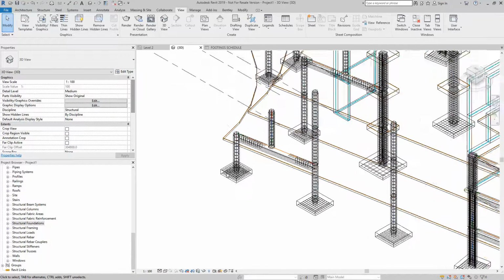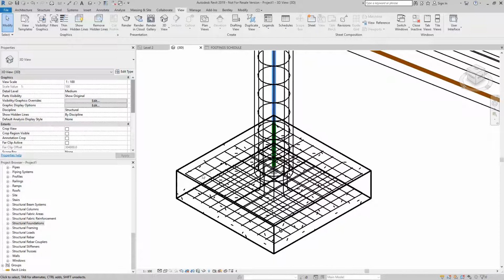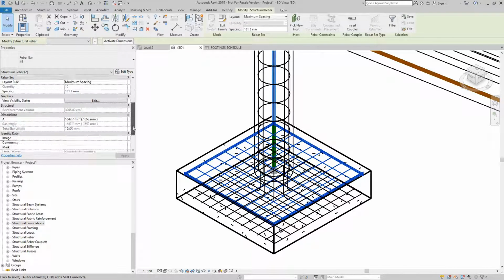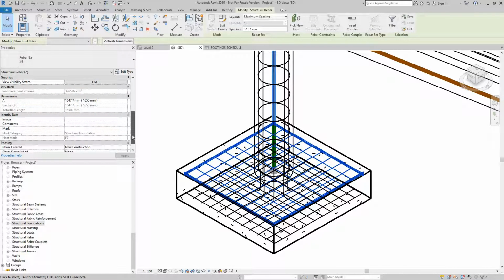We're separating the reinforcing for bottom layer only compared to top layer only. So this is a special prerequisite step you have to do if you have top reinforcing. Select your top reinforcing in your Revit model. You can select them en masse or per instance basis. And in comments, let's include something recognizable we can use to filter out in our schedule. So in here, I'm just going to add the word top and hit apply.